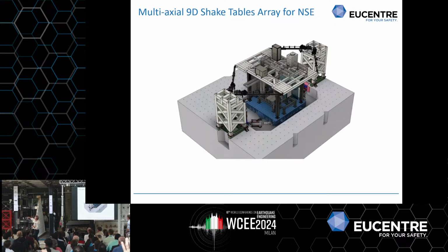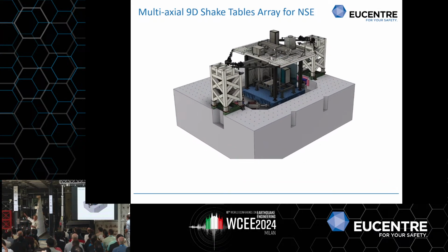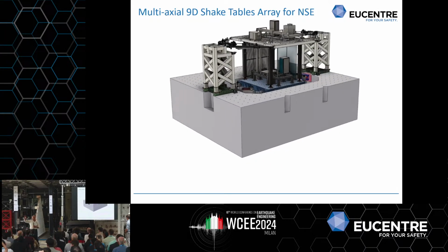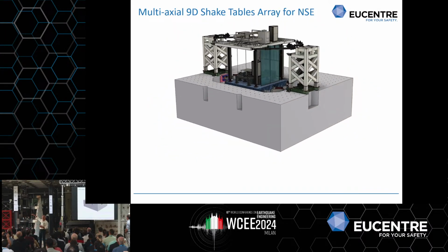So we have designed those towers, which have something like 70 Hertz frequency to be completely outside the frequency of operation of the table. And those actuators that you see on top there, that are essentially oriented like the lower actuators, those actuators have 2 meters displacement capacity. So the upper shake table could be moved independently in the 2 horizontal directions and around the vertical axis.